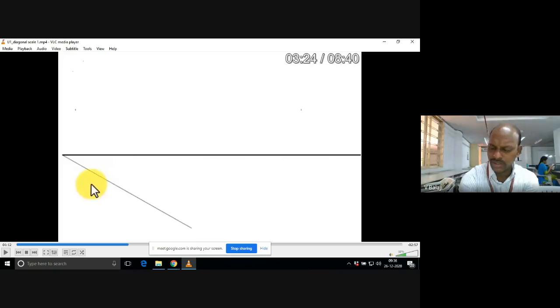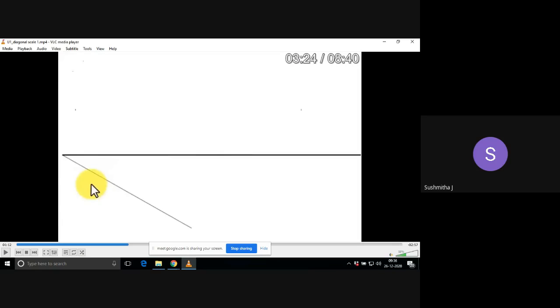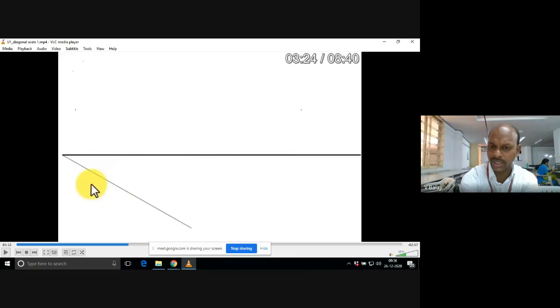Yes, 10 kilometers. So we are dividing this line into 10 equal parts, which means each part will be actually 1 kilometer. That is very important. Forget about the 20 centimeter you have calculated, but you have to take exactly a 20 centimeter line.